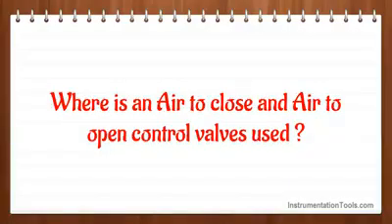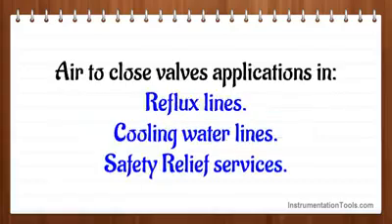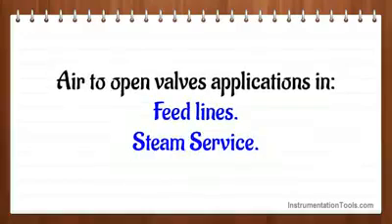Where are air-to-close and air-to-open control valves used? Air-to-close valves are applied in reflux lines, cooling water lines, and safety relief services. Air-to-open valves are applied in feed lines and steam service.